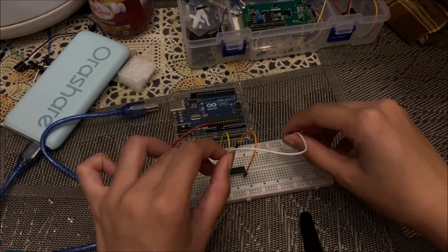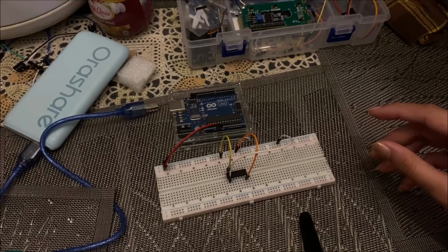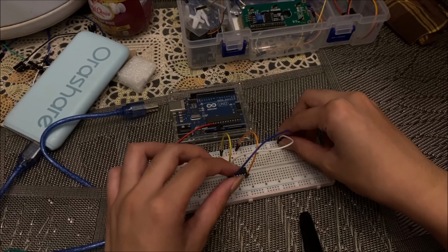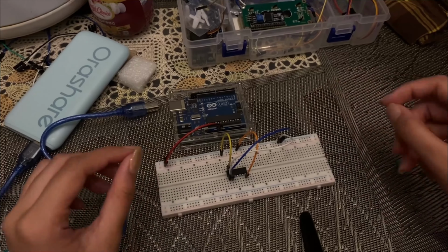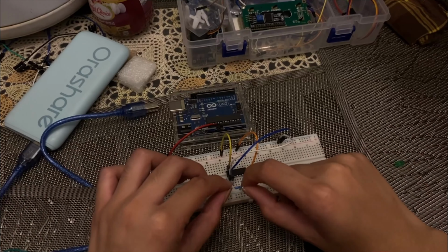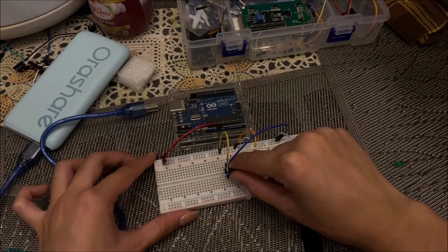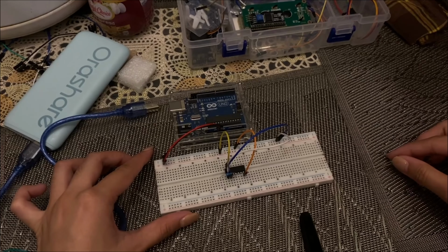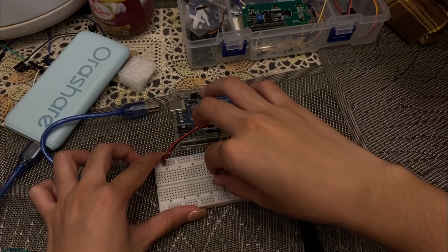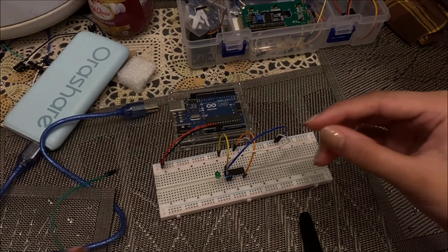Inputs on pin 1 and pin 2 are connected to either 5 volts or ground using jumper wires. Pin 3 goes through a resistor to the LED and the LED returns to GND.